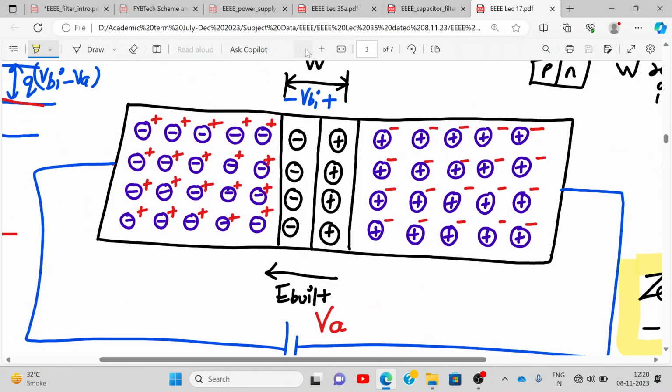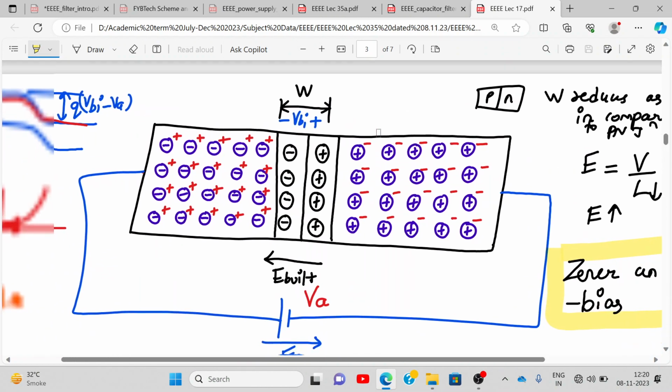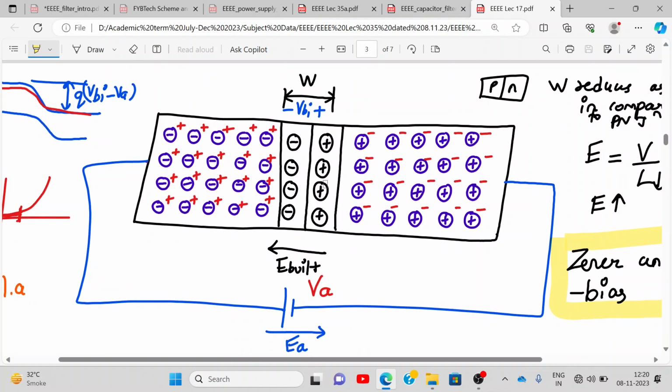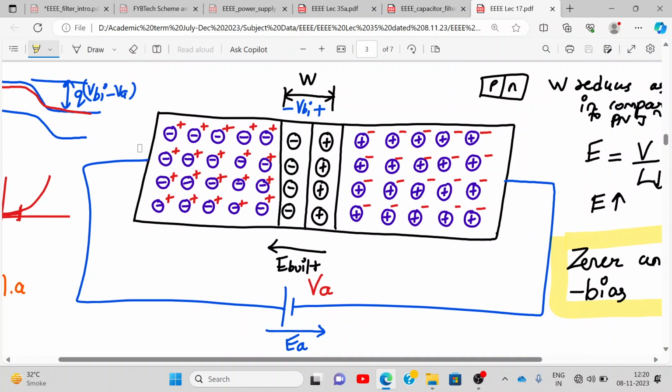See, this is what happens. Now, I told you in forward bias it's exactly the same as your PN junction. What is the difference? The V_BI barrier, which you see over here, W is slightly smaller in a Zener diode compared to a PN junction diode. So tell me, what is this? Describe. Tell me, what do you see over here? More carriers on either side of the junction.